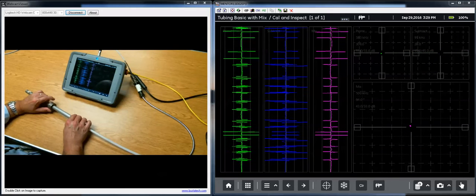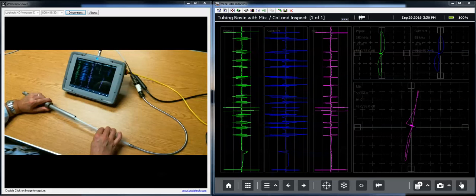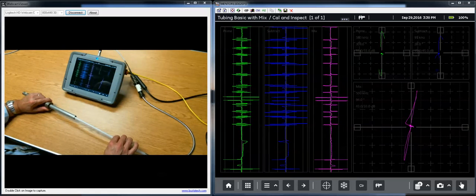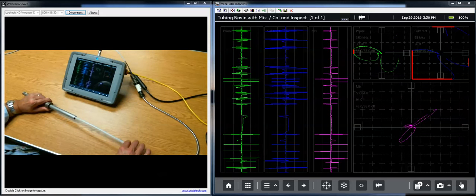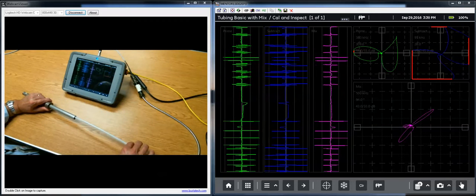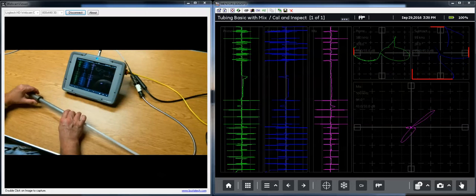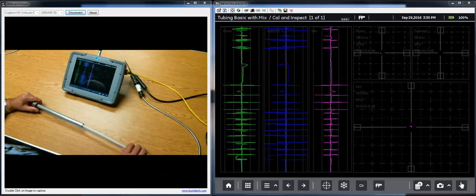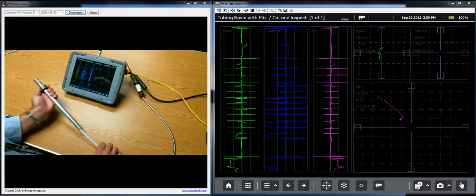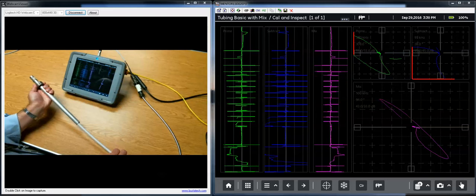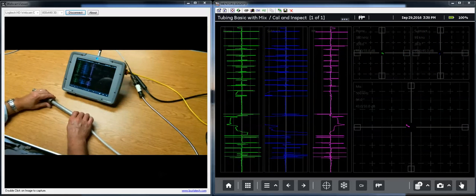a very neat flaw. I can put the flaw right at the edge of the tube support plate. And still, clean flaw. You see a little bit of change of shape of the signal, but not appreciable, and you can still gate on that quite well. Take our plate and put an edge right over the through hole. This way. There you go. Okay, so that's all there was to mix.